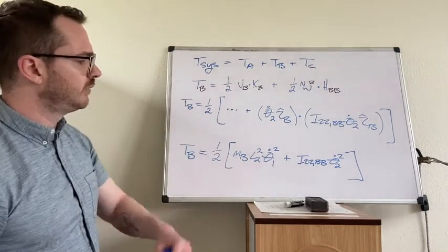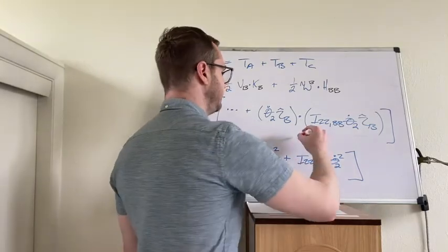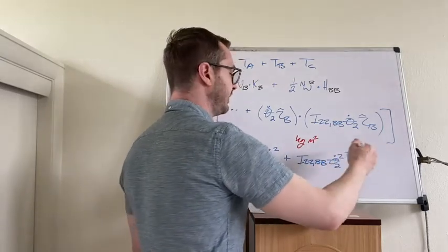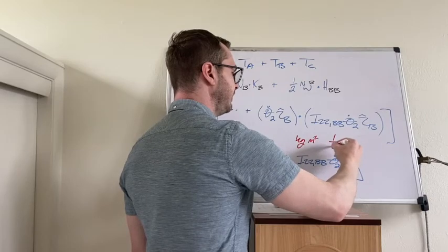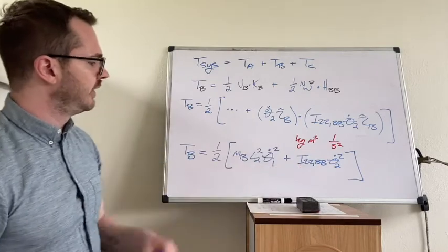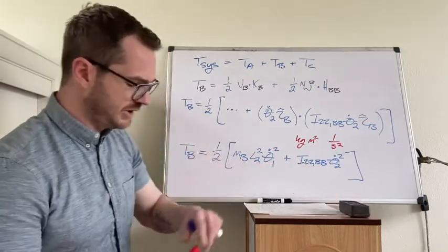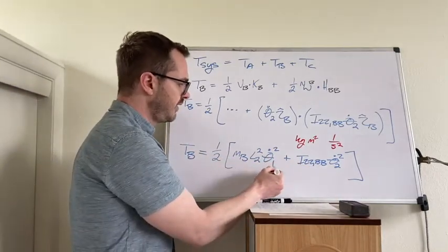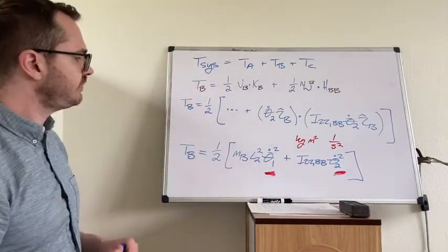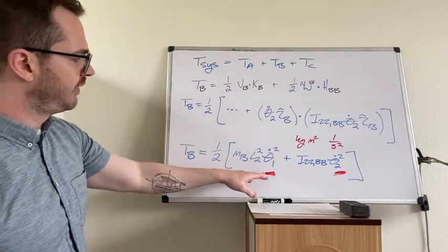We could also look at this one in terms of units if you're concerned about units. The units of inertia are kilogram meter squared. The units of the angular velocity, radians per second. So this becomes 1/seconds squared. Kilogram meter squared per second squared. This one's also a joule. Okay, interesting point on this one. Notice that this energy is a function of theta 1 dot and also theta 2 dot. This expression has two of the generalized speeds in the expression, theta 1 dot, theta 2 dot.